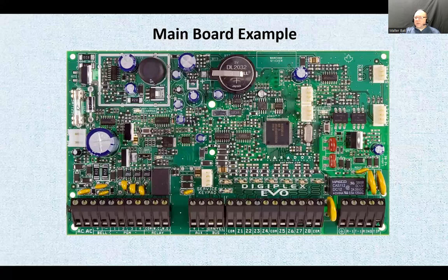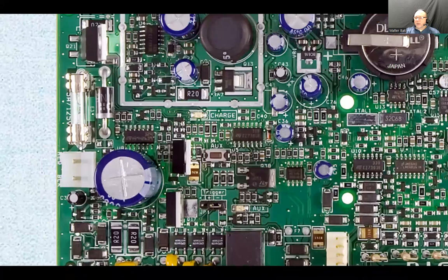All right, and of course here is the fuse, and in this particular system, this fuse goes together with the backup battery here. If you plug this in, the terminals will be plus 12 and, well, neutral, black and red. So here's a 0, here's plus 12 volts DC. And this thing will be constantly charging the battery. And if the battery is needed, then the battery is going to provide the power for it. So it's also a battery charger.